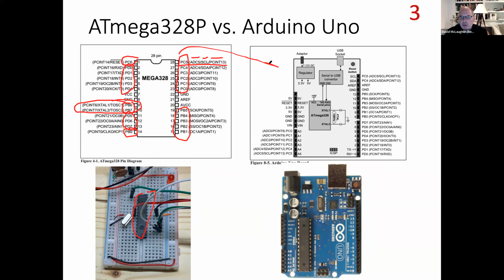All of that is also represented over here on the Arduino Uno side, right? And they're actually grouped a little more easily for us on the Arduino Uno. There's 0 through 7 there. All right, so that just corresponds to these. So you stick a wire in those, and you're connecting to port D, pins 0 through 7. Okay, and then we have PB0 through PB5. And you'll notice that on the Arduino, you don't have access to PB 6 and 7. It's because they're taken up by that crystal right there. Okay, and then you also have port C, pins 0 through 5 here, right? So this is how we would access all those. And I'll show you examples where we're connecting LEDs and things to those. So that's the physical part of the ports.